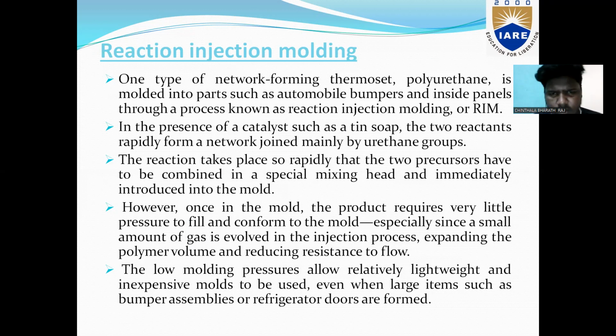However, once in the mold, the product requires very little pressure to fill and conform to the mold, especially since a small amount of gas is involved in the injection process, expanding the polymer volume and reducing resistance to flow. The low molding pressure allows relatively lightweight and inexpensive molds to be used even when large items such as bumper assemblies or refrigerator doors are formed.